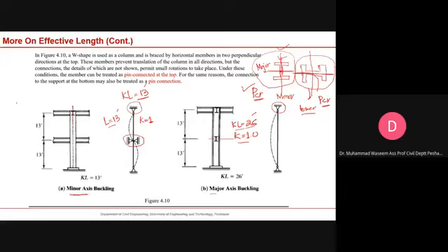If you remember, in order to design the compression member, we use two design aids. One aid was from table 4.1 to 4.20, I guess, and we call that the column load tables. And we also used another design aid from the manual, that was table 4.22.